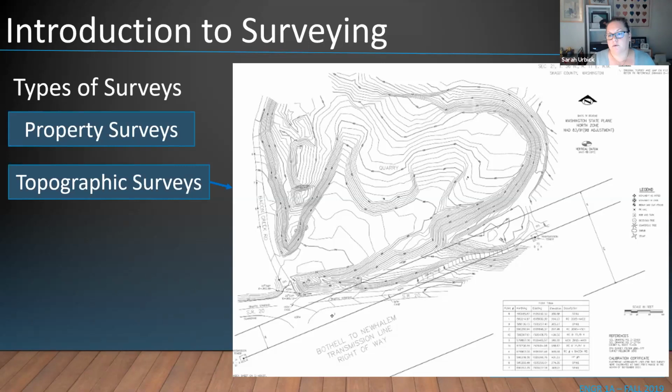What I wanted to do was get 2 topos, and maybe we'll still do it, but where you see the congregation of a whole bunch of lines really close together, that's where it starts to get steep. So that's what we need to figure out is, am I talking about a hilltop or a tabletop? Where do you want to build your house? Hilltop? Tabletop. Tabletop's going to be a nice, easy way to go. Okay.